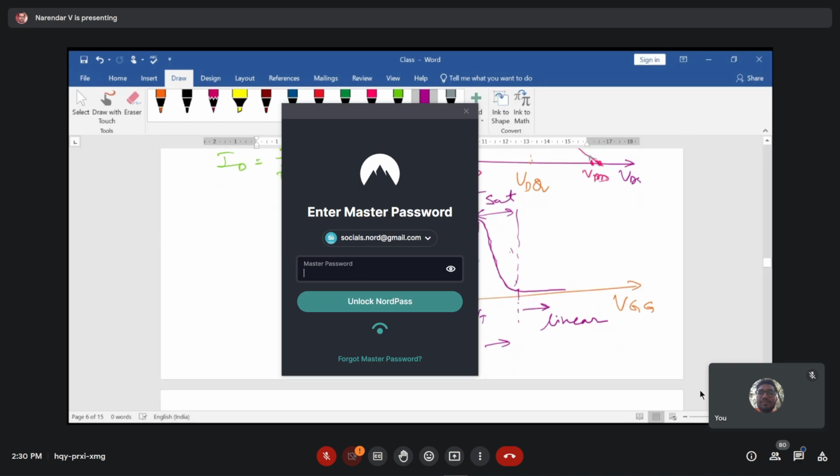Now, there is an input variation, a small signal. This is referred to as a DC voltage, and added with the DC voltage there is a small signal which you are going to apply here, which is smaller in amplitude. Let me draw the small signal here, exactly at the center of this. If you draw the small signal, it is very small in magnitude, but correspondingly you can see that there is a variation in your current which is very huge.